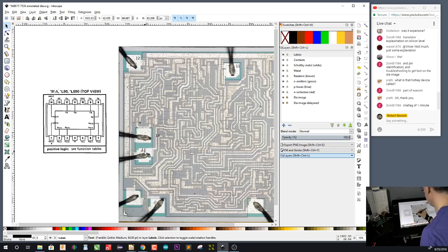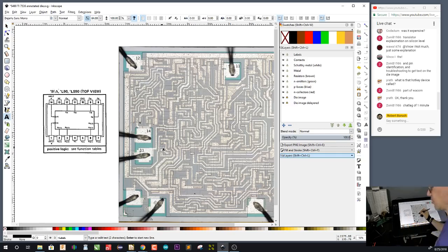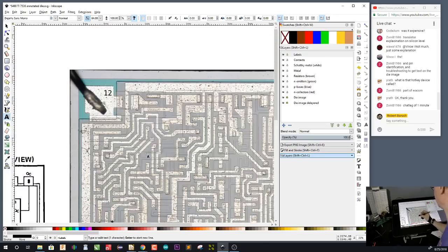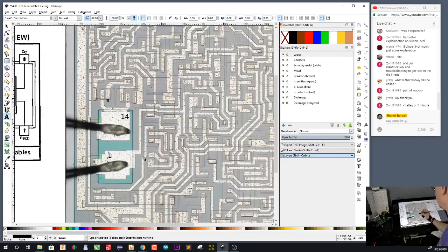And sometimes, unfortunately, you get a double press. So that's kind of what happened there. This is pin 1. Now this is also something interesting that you should know. Pin 1 usually, the pad for pin 1 usually looks different from all other pads. So you can see that these pads are kind of square. Up here, they're kind of square. But this one has, you know, a lot of zigzags, and that's what the chip designers typically do to label